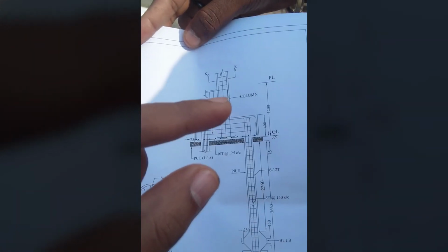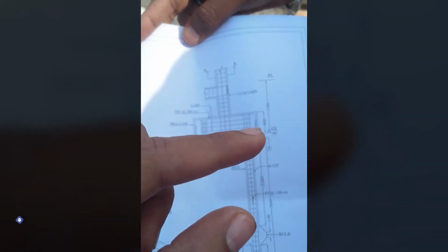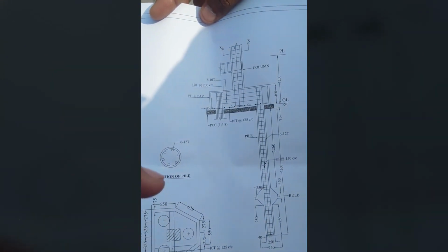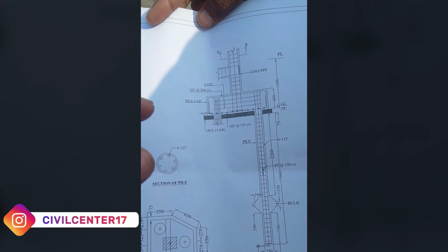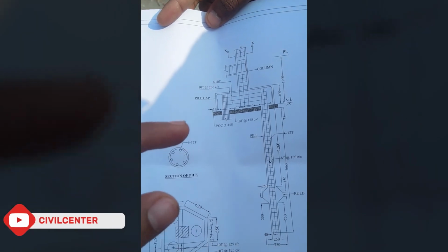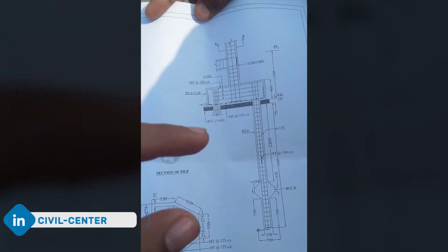This is the plinth level where the plinth beam will start. You can see this is denoted by PL, and this is the GL. One important thing to be observed while executing this drawing on site is that the site should be properly leveled. That is, the base level of all the pile caps should be the same, because if the base of the pile caps is not the same, it can result in eccentric loading or cause problems. So we should properly level the ground, and while casting the pile caps we should ensure that all the bases of the pile caps are at the same level.